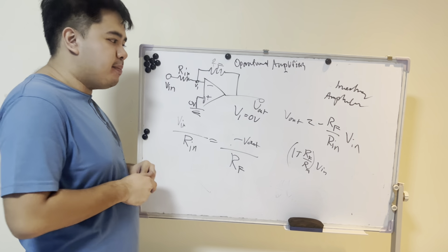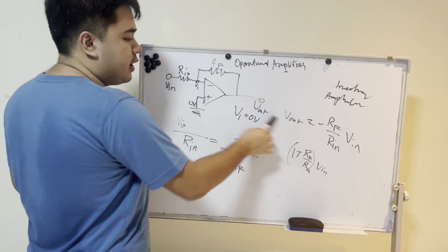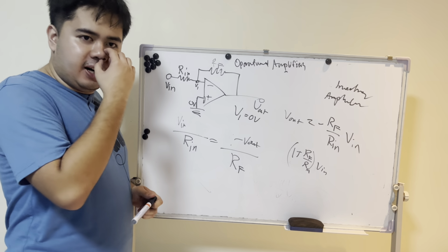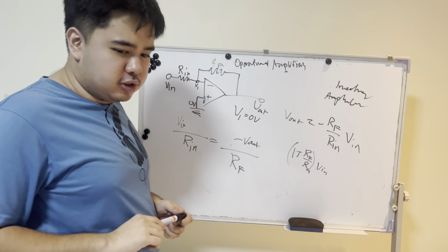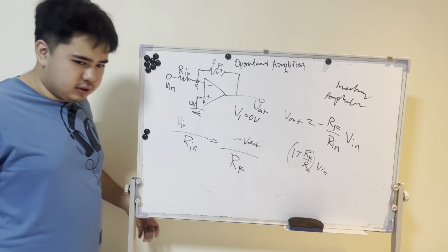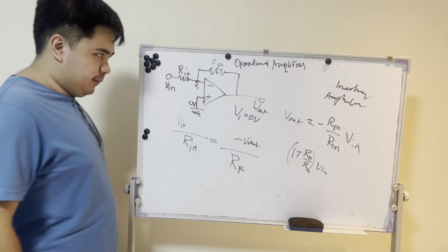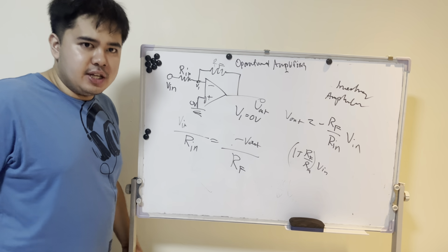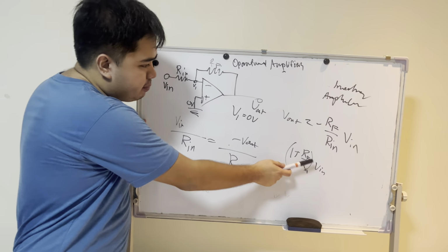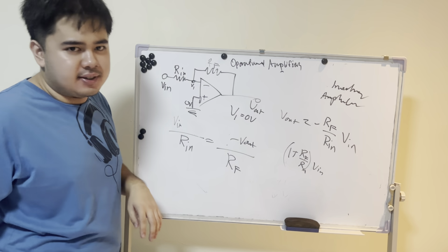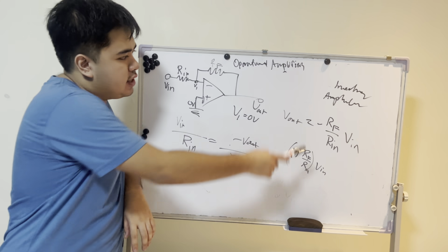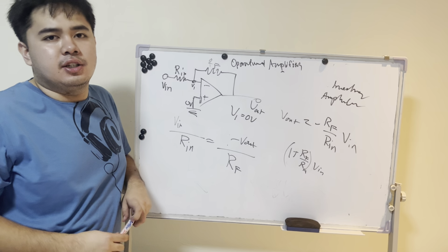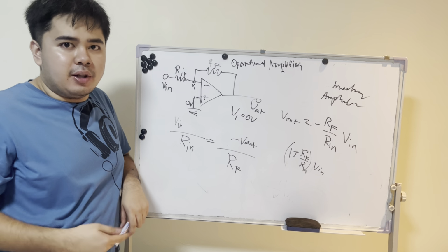But there is a problem with this formula, it's the 1. That's tricky because we want to control the voltages. If we want, say, 20 gain, we need to set up 19 gain here, and that's not that easy. But in here, we can set negative 20 gain. So that's still 20 gain.